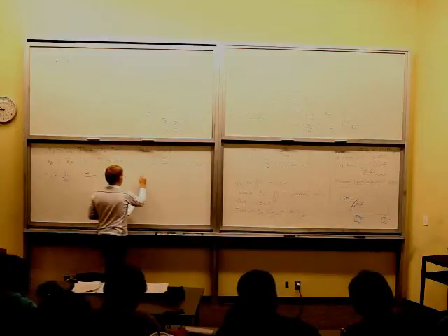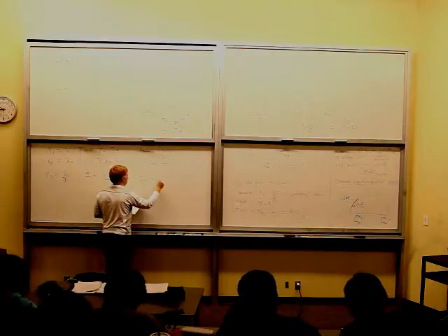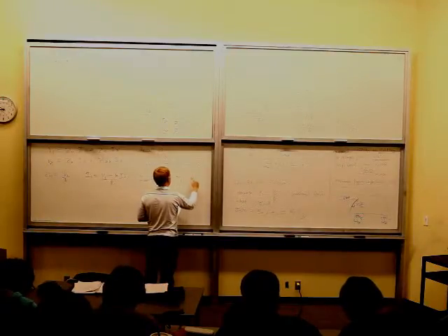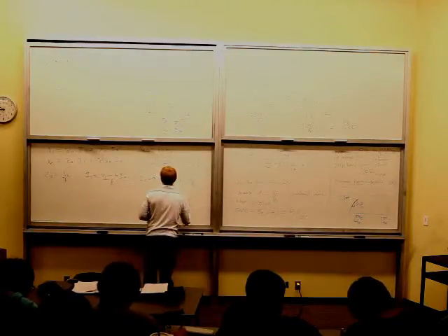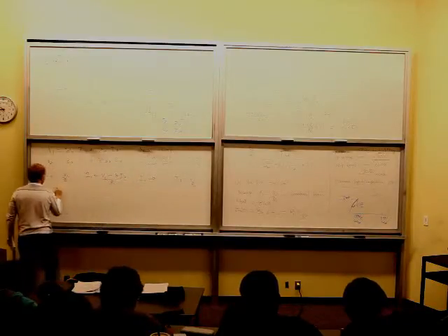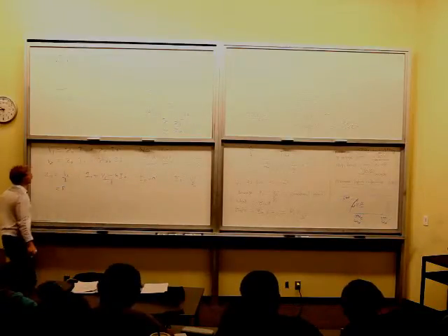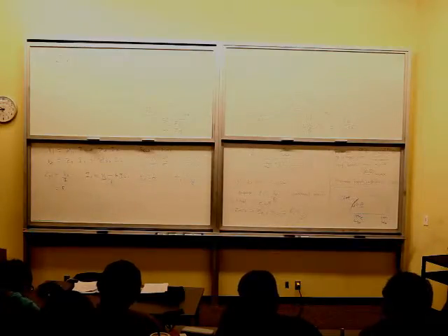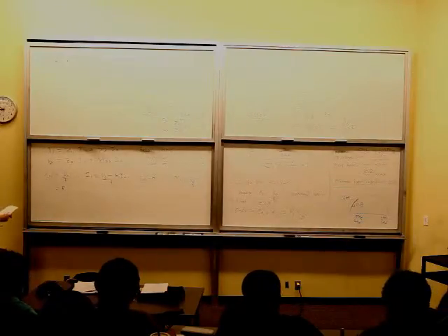But since I2 equals 0, therefore I1 equals V1 over R1. Rearrange that, we end up with Z11 equals R1. So that one was pretty easy. If you saw that I2 was 0, you could just shut that off mentally, and you know that a voltage source that's off just looks like a short, right? So it just looks like R1 when you look in there.